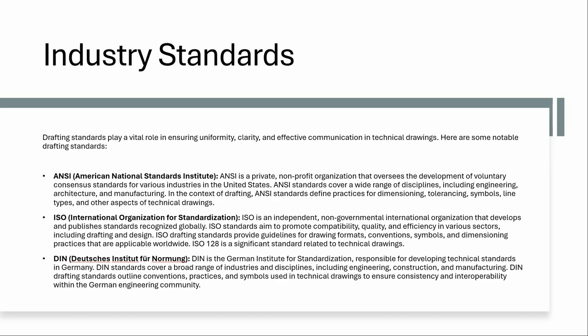Now, if you put 15 decimal points on your lat/long for a benchmark on a survey in your drafting product and stamp that, you're claiming that's how accurate your measurement is, down to that tiny, truly unmeasurable point. That's not even going to be within the tolerance or the accuracy of the equipment that's used to collect it. So understanding significant digits, understanding where you should be setting your decimal places, is going to be important for you as a professional,